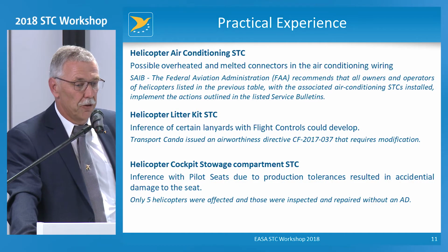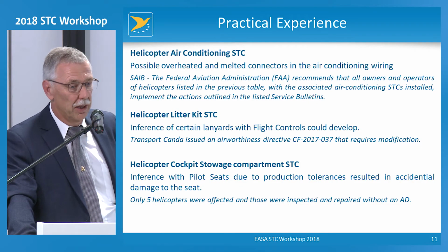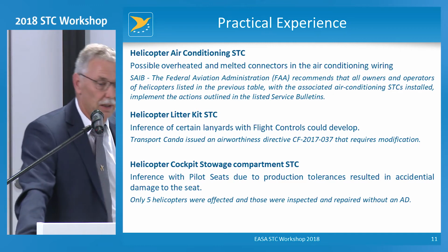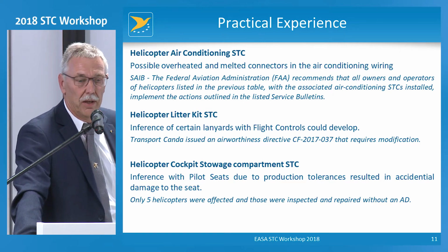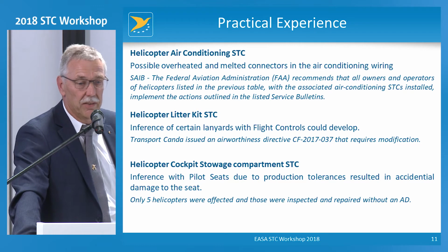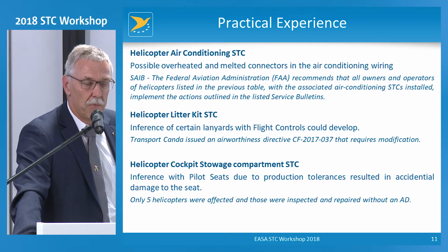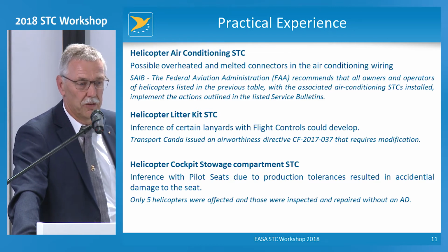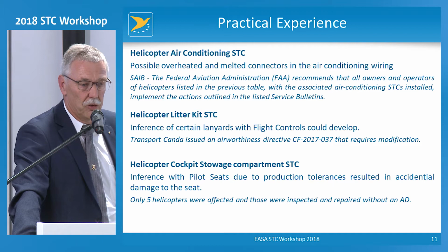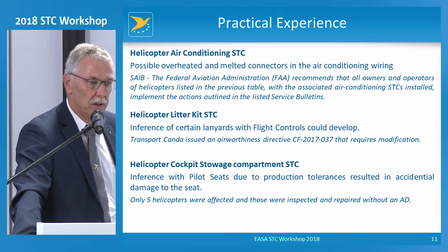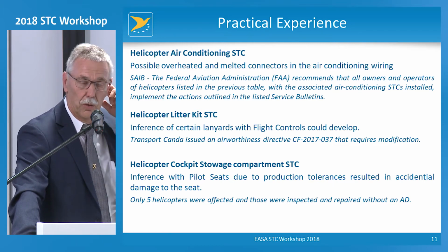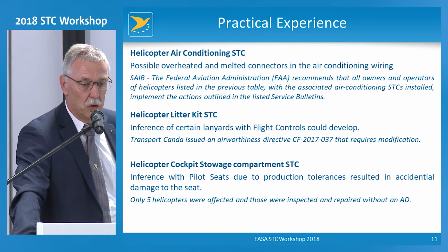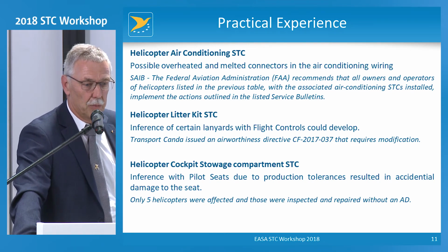Then some examples from helicopters. The first one is again something electrical, overheated and melted connectors in the air conditioning wiring. In this case, it was also action by the FAA, and they decided that this is not worth an AD, but they issued an SAIB, which is similar to our SIB, and recommends that the helicopters are changed and the systems are improved.